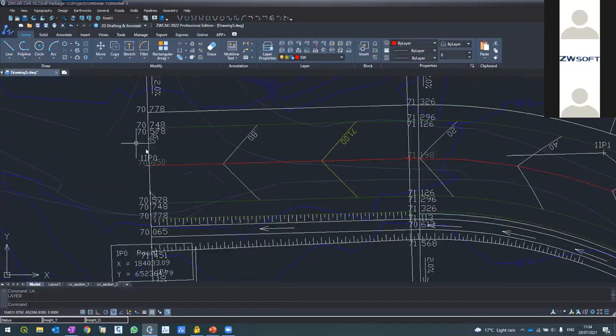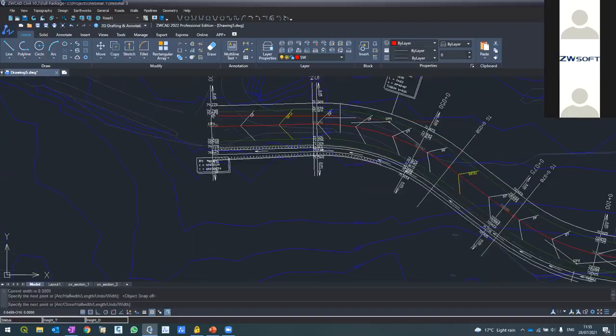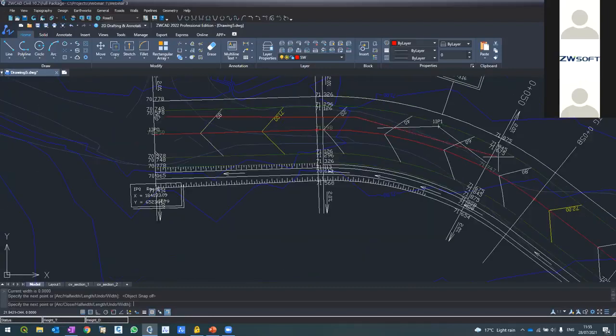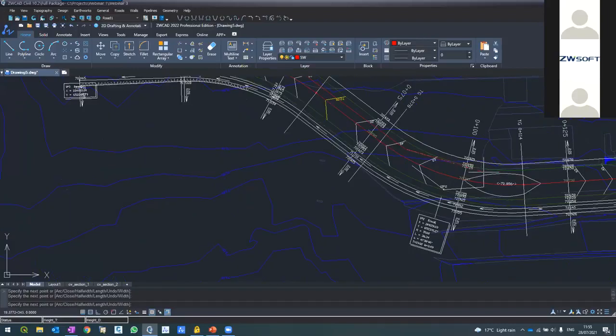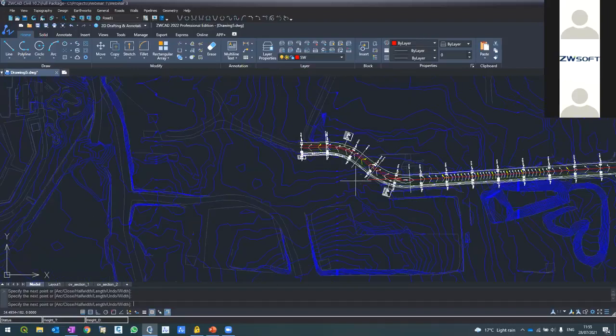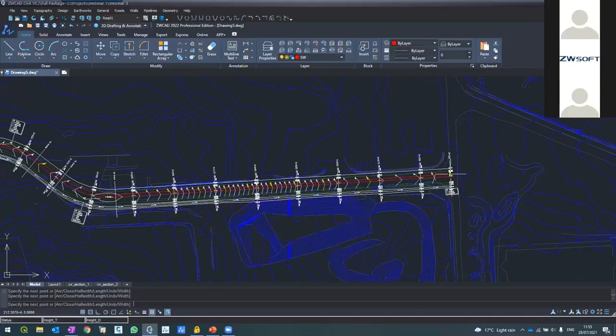Now, so my first pipeline, we start somewhere here in the junction, let's say near this side of the road, goes all the way toward here. This is one manhole. Another manhole will be here. Another one will be here. Another one will be here. And going to the end of the road, let's say each 40 meters I would put a manhole.